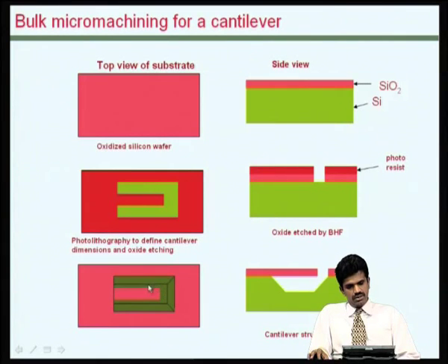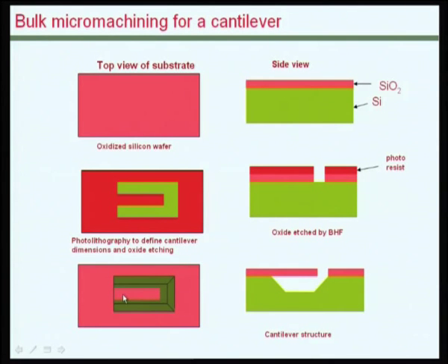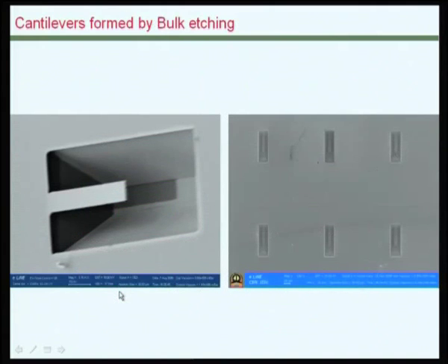In this corner, the atoms belonging to this plane or this plane are partially covered, and hence these corners will get attacked, and if you left it for long enough, there will be undercut, and this structure can remain freestanding at the end of the etch process. This is successfully utilized in realizing arrays of cantilever geometries in our labs.